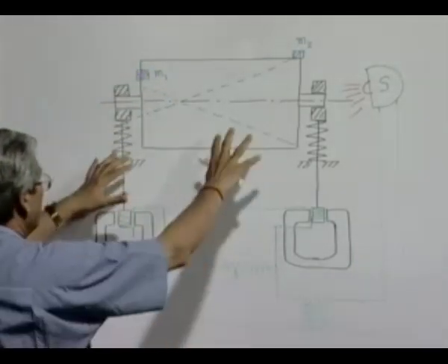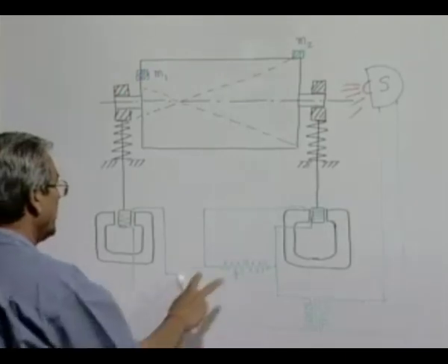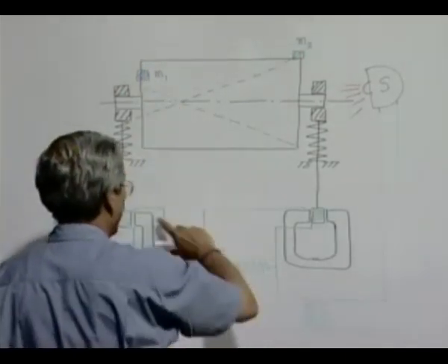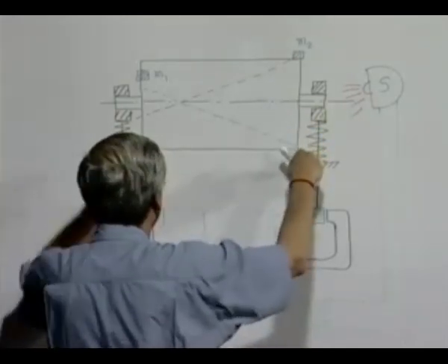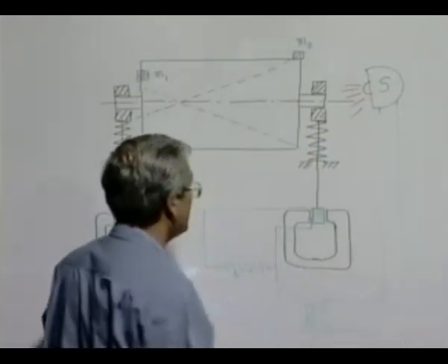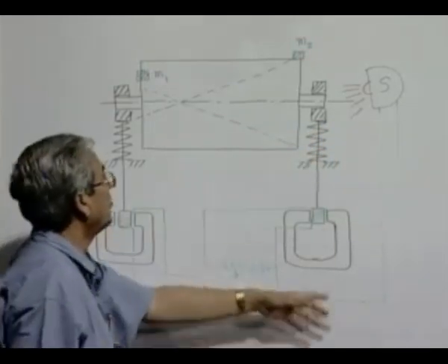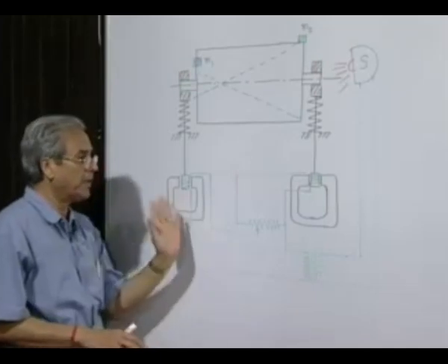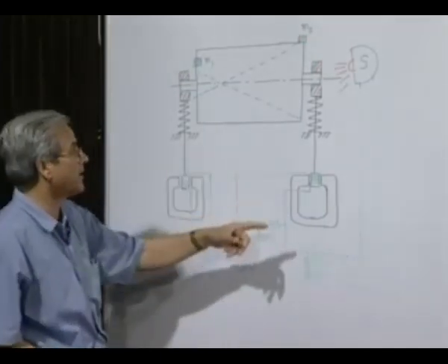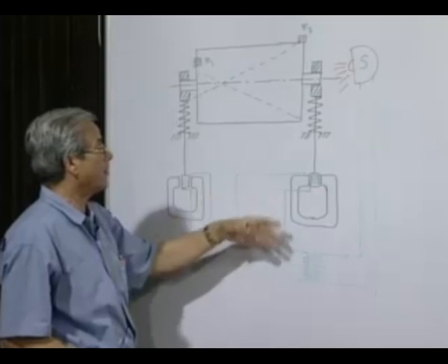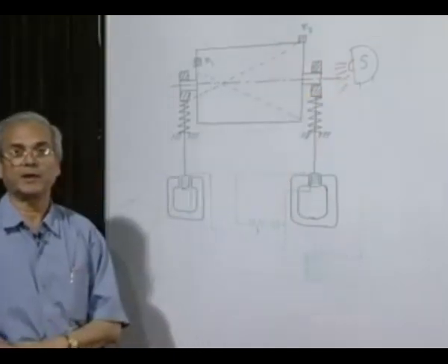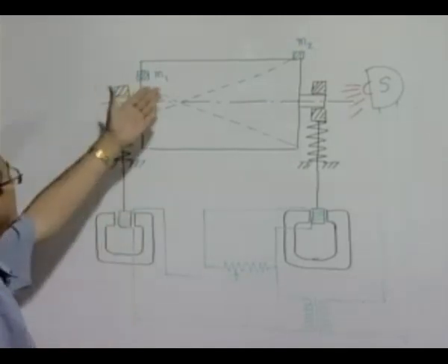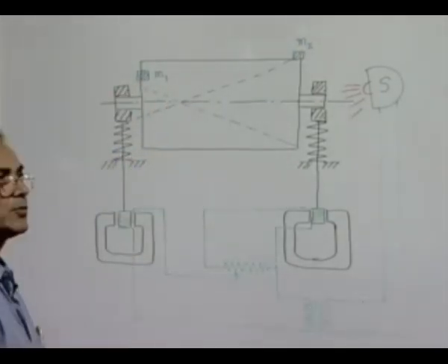Similarly, we can have another circuit where we have suitably compensated the voltage generated here, so that the circuit will produce the flashing only as far as this particular mass's effect is concerned. Thus, depending on which circuit we are using, we can find out the angular position of this and the angular position of this using the stroboscopic method. And by suitable calibration, this can also tell us about the magnitude of the two unbalances present.